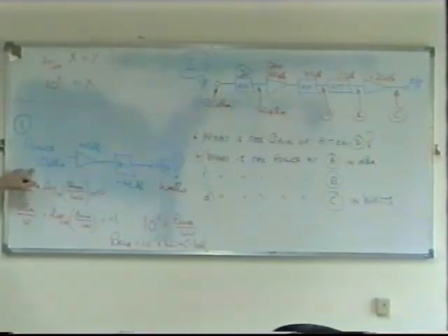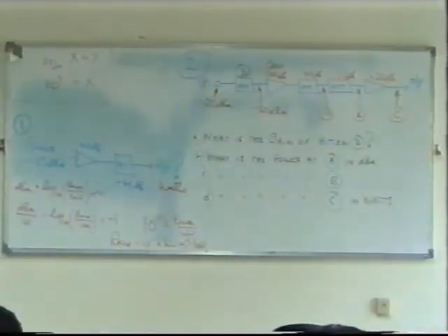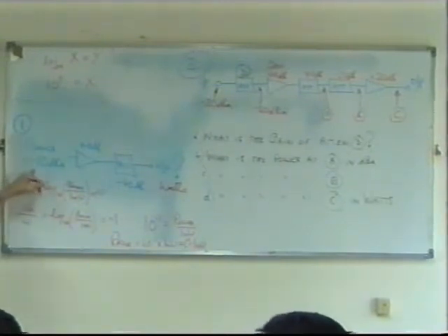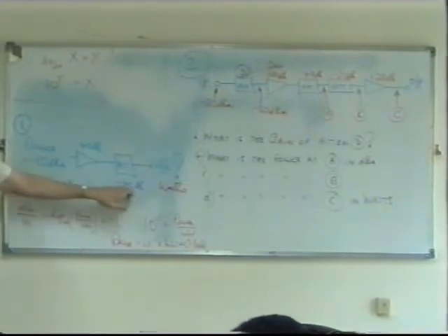Okay, so if you get minus 10 dBm, for example, as you say, Abdul, anything negative, when we're talking about dBm, it means less than 1 milliwatt. It doesn't mean to say a negative power, of course. There's no such thing. All powers are positive. It can be very small, but it is a positive number. So you must always remember this. And this, of course, is the feature of using logarithms. This is a logarithmic measure of power. dBs are a logarithmic ratio of powers.